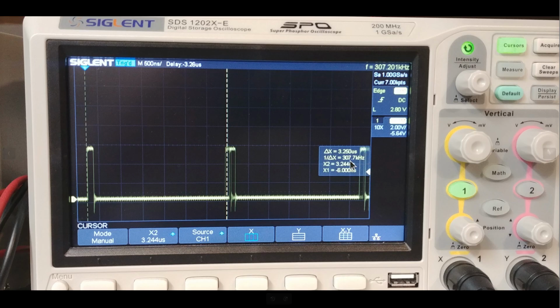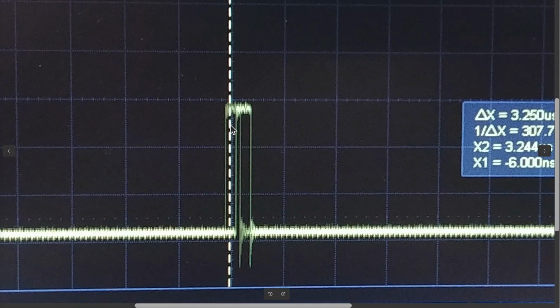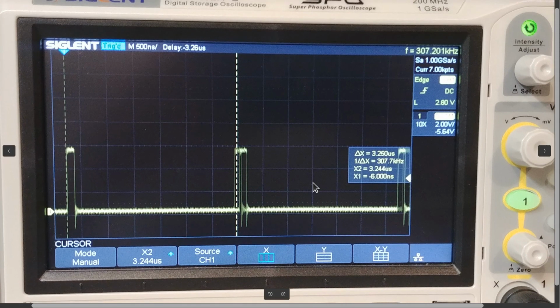What do we got here? I guess at this resolution, this number here is rounded up slightly. The point is that this cursor here is between the leading edge of the 1 cycle here as we zoom in, and we can then see, right? So this cursor is between the leading edge of this signal here and the one that comes after it over there. So it turns out that if you walk through the waves and you think about it for 10 minutes, it'll become obvious that in order for this to maintain the proper frequency, occasionally some of them will be a little bit long, some of them will be a little bit short, and it'll jitter back and forth like this. You can see the next one jittering over here, okay?